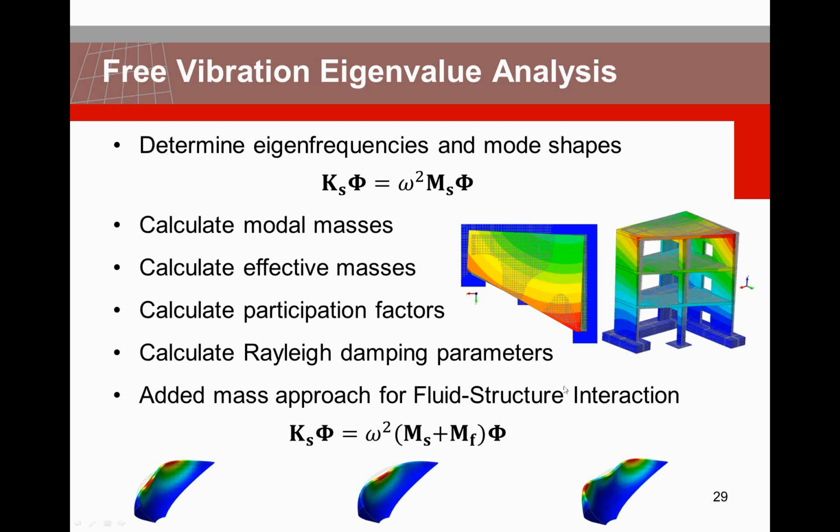You can calculate your Rayleigh damping parameters, or let the application calculate your Rayleigh damping parameters, based on the found eigenfrequencies or preset frequencies and damping ratios. For the fluid structure one, as already said, your mass matrix is extended with the added mass from the fluid. You see some images of how mode shapes can be visualized in this way with a contour plot, here for a dam and here for a reinforced concrete structure.